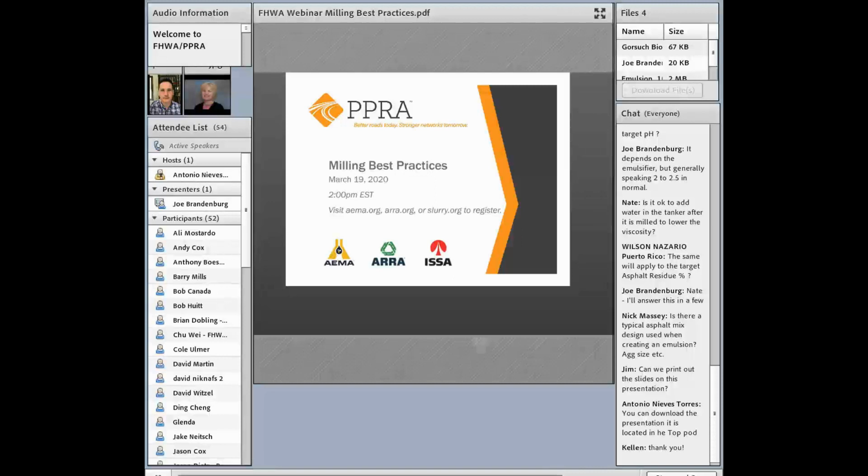Perfect. Next question. For a CSS 1 HP emulsion, what will be the ideal or required targeted pH? Kristen, you can jump on this, but the one thing I've seen is typically it's 2 to 2.5, but it depends on the emulsifier and the stone. And Christine, you want to add to that? Yeah, typically you start off at 2, but you might have to adjust it to match the reactivity of the stone.